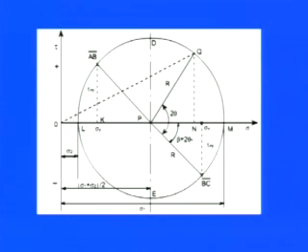So here you have both the maximum and minimum values of normal stress, because only the normal stress component is there on this plane. So this plane is the principal plane, where the principal stresses act. We can simply note the maximum value of the principal stress, sigma 1. Once you know the maximum value, simply take it on the x axis, and if you know sigma 2, the minimum value of the principal stress, put sigma 2 as well. Now you have sigma 1 and sigma 2, and wherever they intersect, you have the full diameter. Here you can simply calculate the coordinates of P, which is nothing but sigma 1 plus sigma 2 by 2.